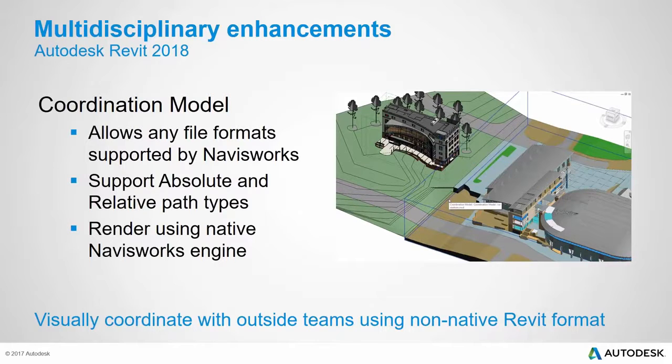Unlike the AutoCAD imports that a lot of us work with, AutoCAD doesn't really let you cut the model very well. With these Navisworks models, it's going to give you a real quality cut of the model, and even have some of the visibility graphics controls that you wouldn't necessarily have with other workflows like IFC or AutoCAD. So it's a great tool set, a great feature that's been added to the Revit 2018 environment.